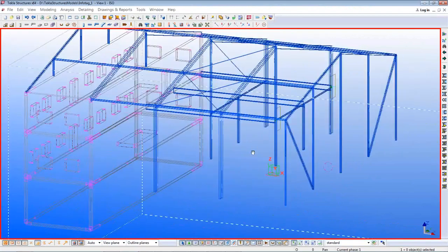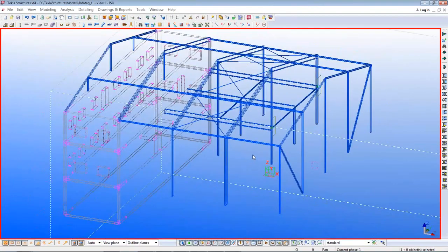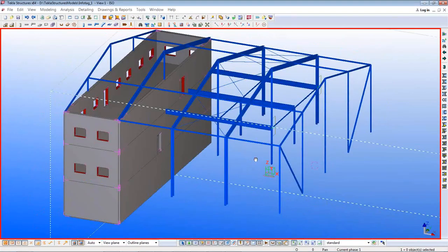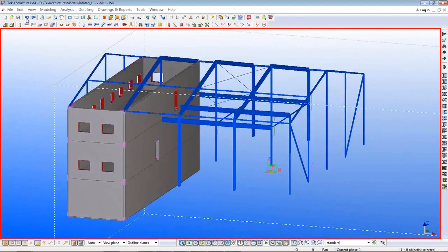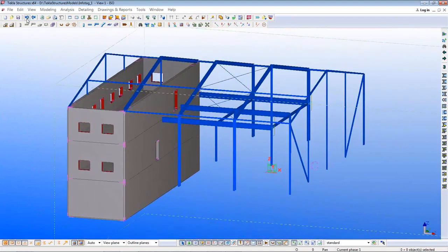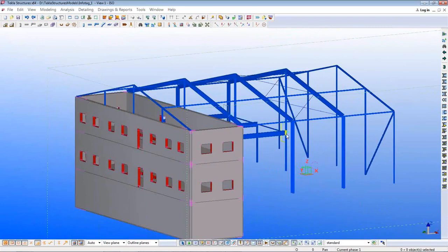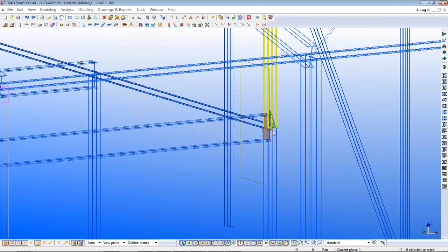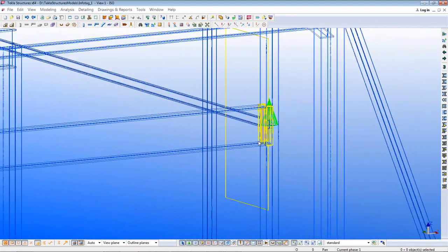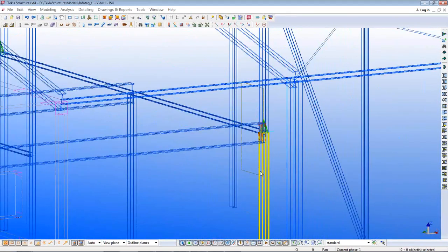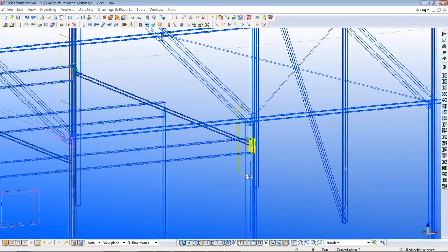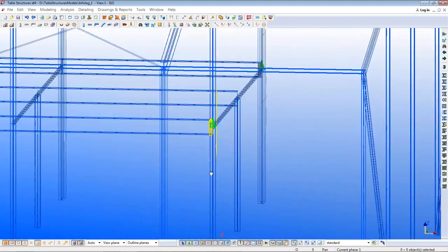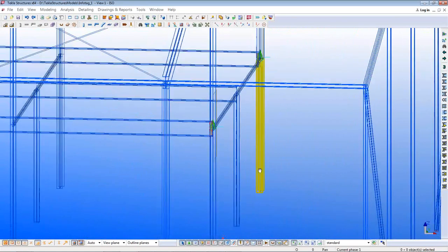And we have here the updated Tekla model. If I do undo, redo, we see here the changes that come in, also the cross-section change. And because Tekla is a parametric program as well, you see here the change is also updated automatically with the connection, and all the work that the designer did during the work of the structural engineer in RFEM is kept, and only the sections are changed.